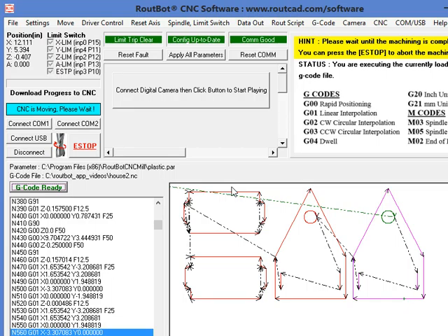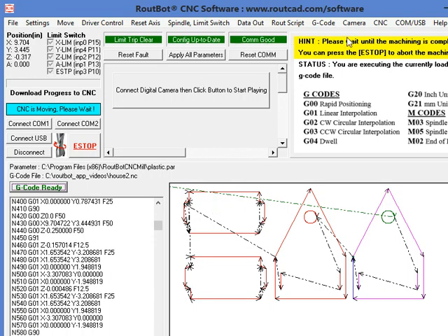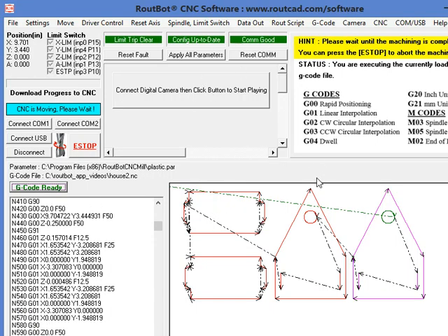What is doing most of the work is the dedicated CNC controller computer that is running the real-time code. So basically, in this way, we can use any other PC which has a parallel port to be a CNC controller. Even an old PC, as long as it is in good working condition, can be a CNC controller. We boot it with the boot CD or the floppy boot drive, and we connect with our connection cable to it. And here we go.